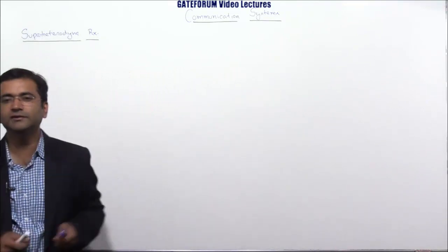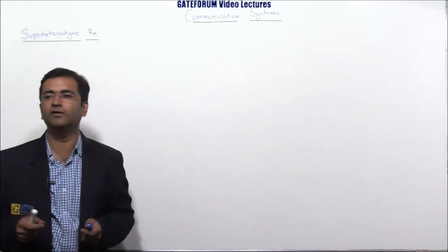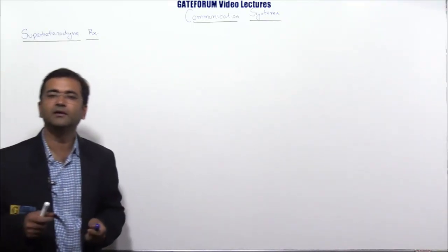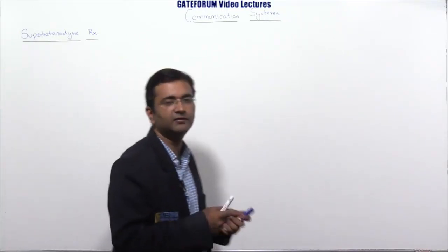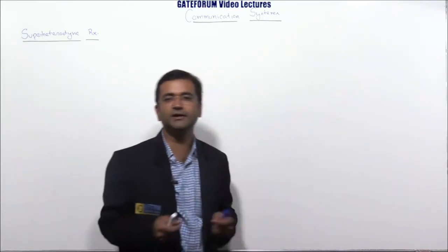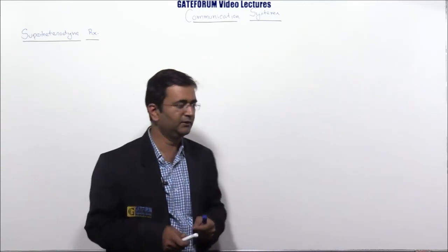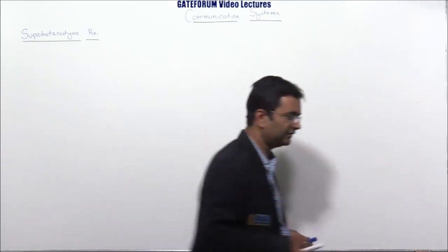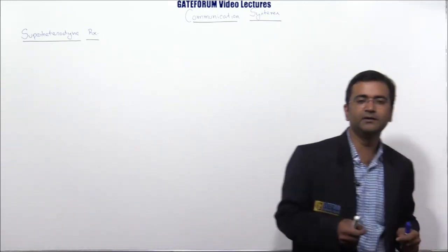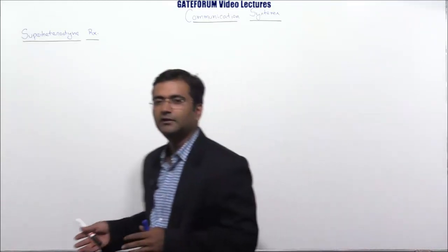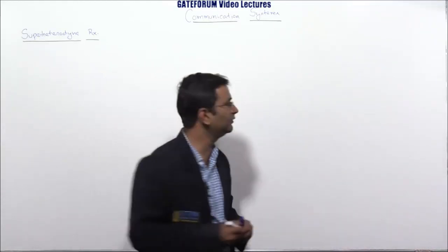The demodulation circuit is totally independent of what frequency is getting transmitted. It depends only on the intermediate frequency, which is one fixed frequency generated at the output of the super heterodyne. So let's see what a super heterodyne circuit is, its block diagram, how it actually works, and the problems associated with it.